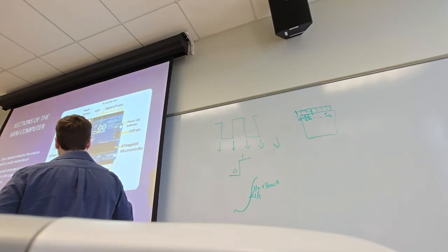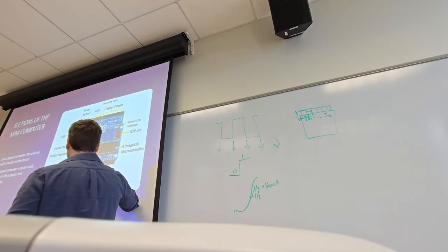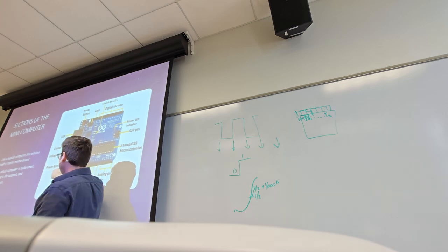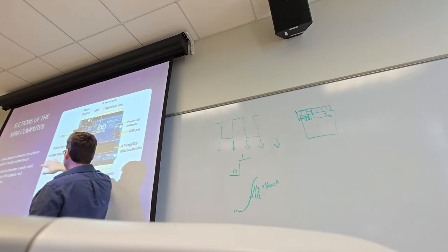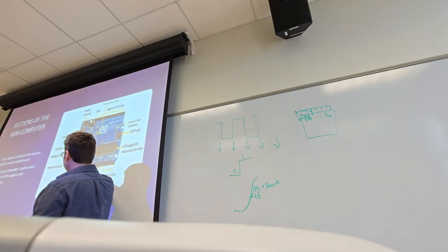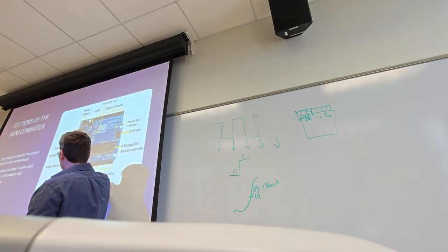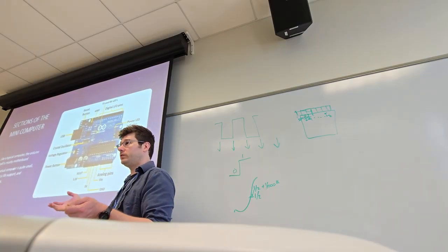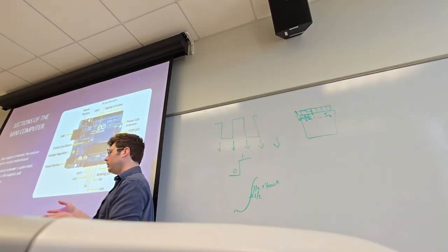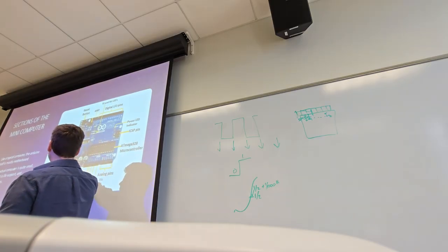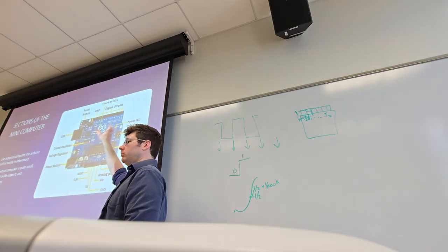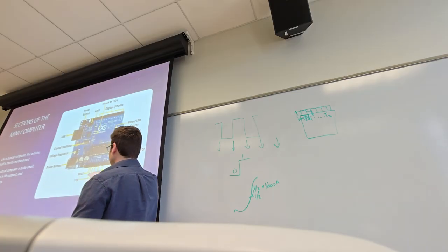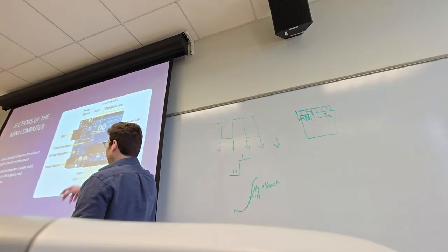The V-in pin is special. The V-in pin is actually attached to this barrel jack. It's just as if we're putting power into this board. Kind of interesting is that we can put up to 12 volts, technically up to 15, on this barrel jack or on this pin. So if you have a wall wart or a DC power supply with a barrel jack at the end of it, you could power this Arduino with that device and it would run and do its thing, power motors, all that good stuff. Or you could put voltage on this pin. Again, say you had a power supply or whatever, you could supply voltage to that pin.